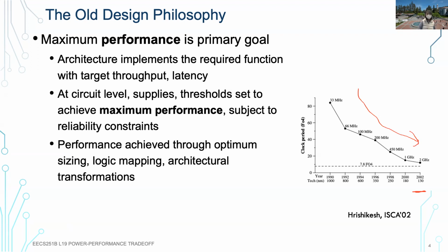So that has always been the focus. There were a lot of studies, even on optimal pipeline depths, and it's more about how we can offset branch prediction latency, right? If it's too deep, besides the power, which is a big concern, there's also performance: the branch prediction penalty will be very high. So a lot of the trade-off was still very heavily focused on the performance point, especially from the architecture side. So all the crazy architecture ideas reached us with very, very deep pipelines.